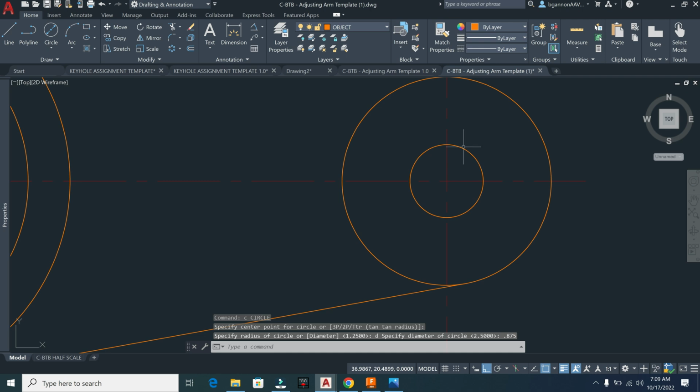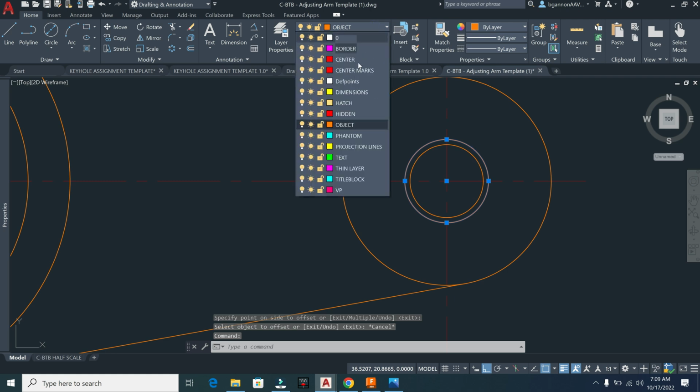And then I want to offset that. Okay, I'm going to offset that by 0.0625, which is also 1/16 of an inch. And this is not on our paper, so you might want to write this on your paper here. This is just showing so we can see it when I go into my layout view. So that's going to be a hidden line right there.